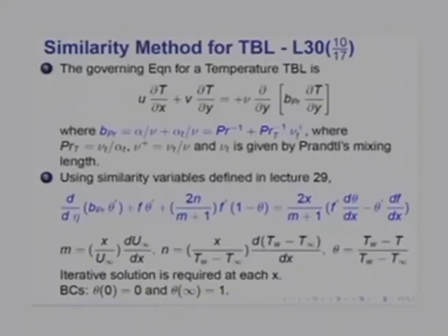With this, I end the methods in which the law of the wall or the integral energy equation is used. And now I turn to the differential equation based methods, and it so happens that you can use similarity type methods for turbulent boundary layers as well.